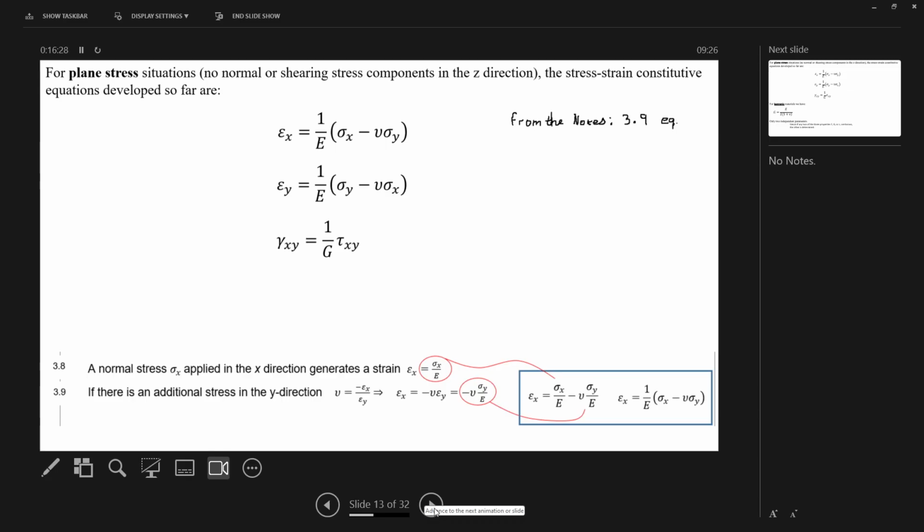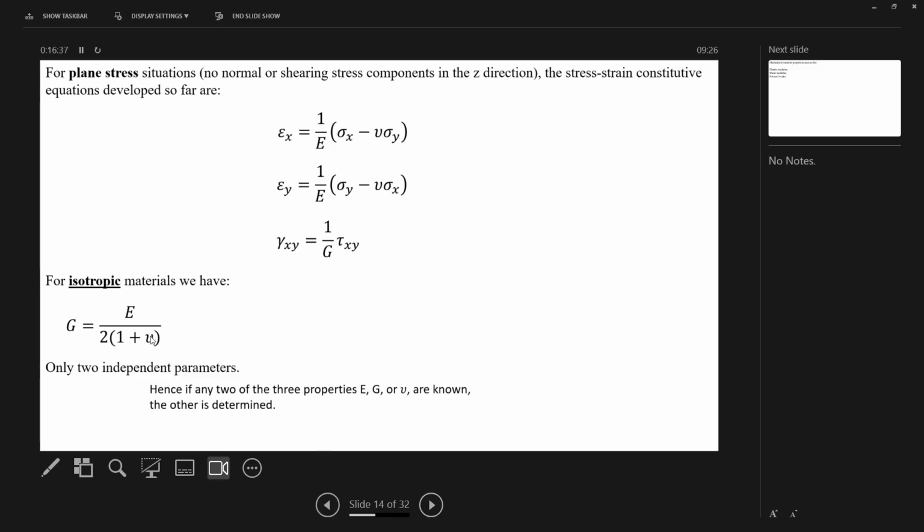Yeah. So from that, we're going to take isotropic material. It just means a material. So this wouldn't be timber. This would be things like metal, or, I hate saying things like concrete because it's not true. Concrete on the bigger picture, right? Like large scale but not small scale. But like steel, this would be true. This means a material that has the same property in any direction, irrespective of how you test it.